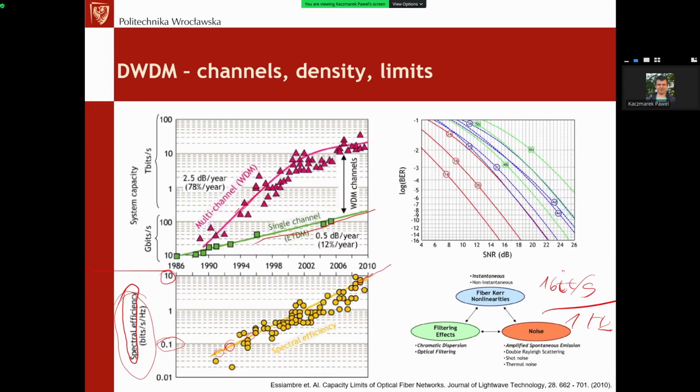and this approach requires different modulation types than simple AM modulation. If we are using AM modulation, the transition from the bandwidth of the modulating signal to the bandwidth of the whole signal after modulation is quite simple, but we can use different approaches, such as QAM modulation, which adds that not only the amplitude is modulated, but also the phase of this optical signal is modulated.